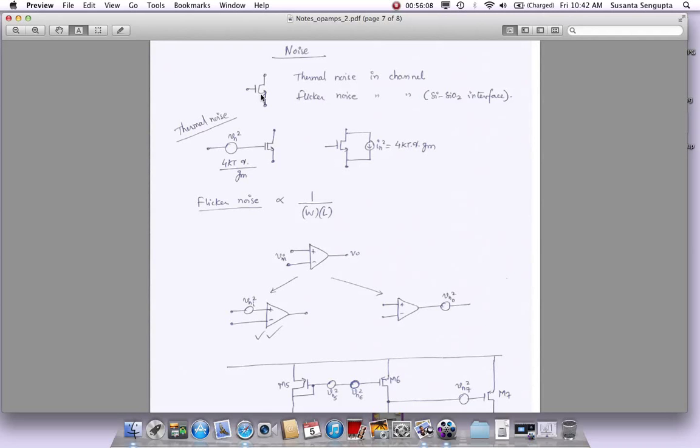They will get generated, and let's say in this case, if it was an electron that got generated in those interface traps, as they also call them, that electron will come and just get swept into this channel, right? That electron did not come from the source. Remember, the current flow of electrons is from source to drain. Somewhere in between we added an extra one, and that acts as a noise.